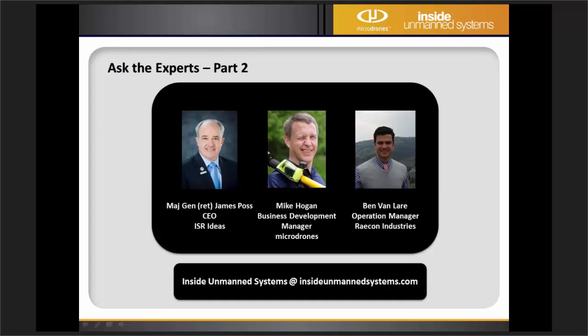Yeah, absolutely. A few of our clients have asked for, especially on the dam safety side, visual inspections. Sometimes when they dewater dam head gates, we can go in and do a visual inspection. You can do a 3D model of a dam face. We've never been asked to provide that, but usually we'll provide a visual inspection of concrete, any corrosion, any cracks that are happening in the concrete. So yeah, it can be done. It's been used quite a bit.